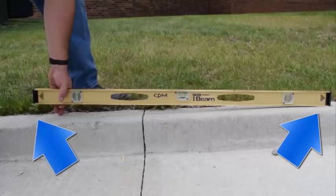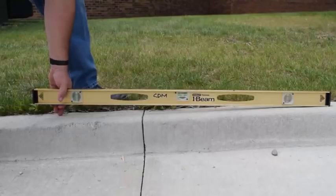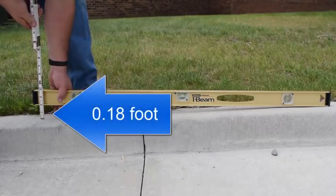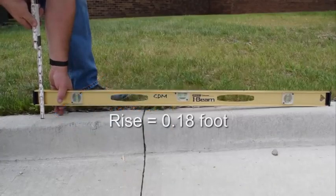The underside of the level is now a reference line we can use. With the bubble centered within the marks, I can measure down from the underside of the level to the concrete. This measurement is 0.18 feet. Since the other end of the level sits on the concrete, the vertical distance between the two ends is 0.18 feet.